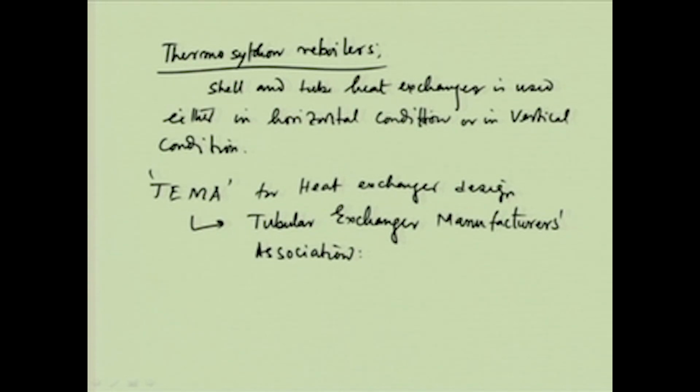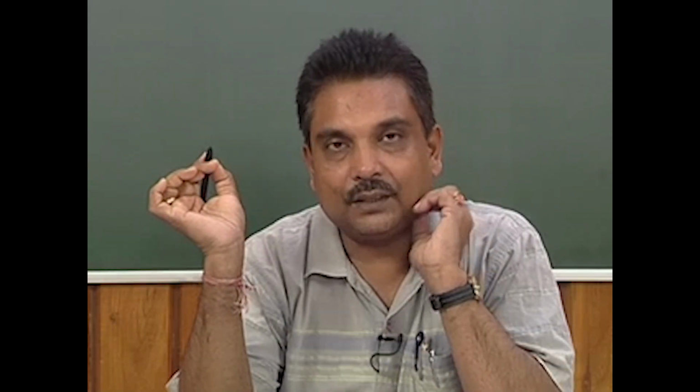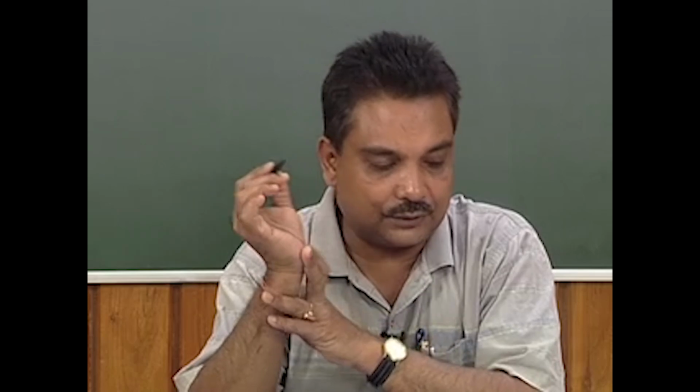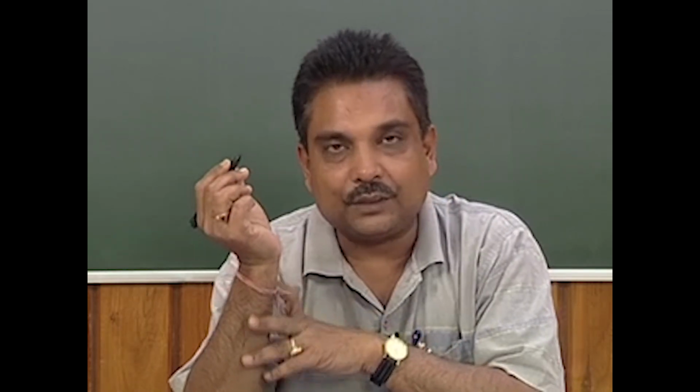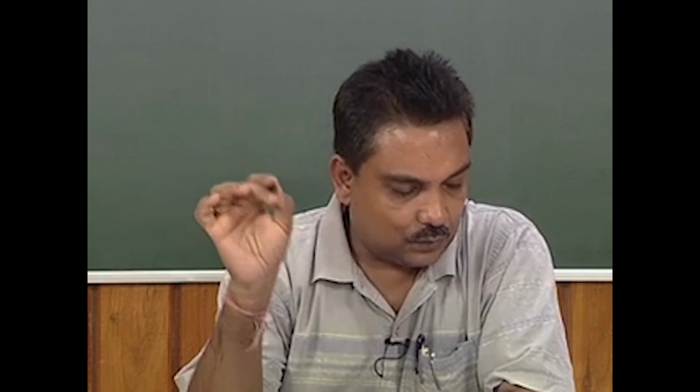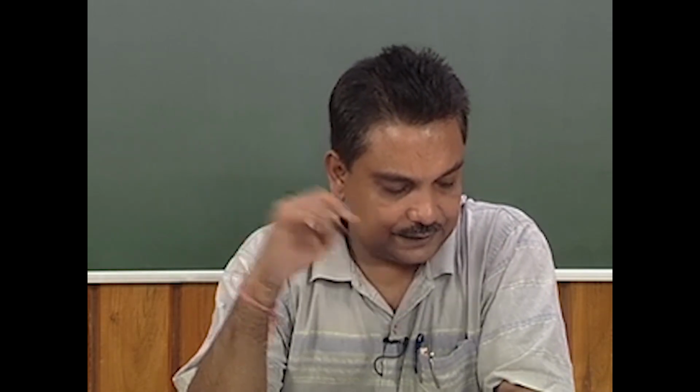Okay. Now, regarding the material of construction, we have told the material of construction depends, for the heat exchangers, upon the kind of operating conditions and the kind of fluids that we are using. And we have to think about the corrosion matters also. Now, one important thing we should say about is the fouling behavior with shell and tube heat exchangers or any other kind of heat exchangers.